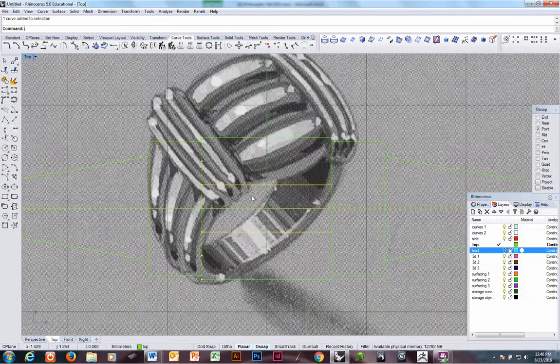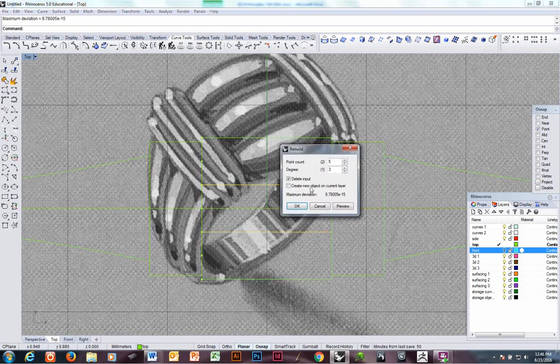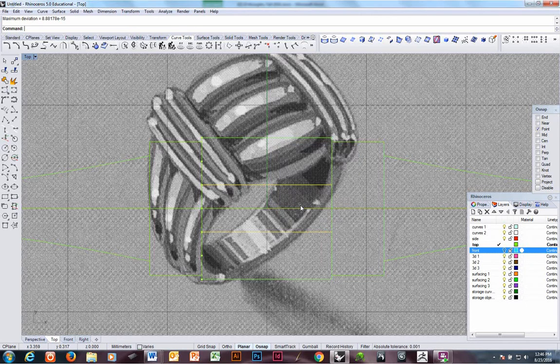And to bulge it, I'm going to do a couple of things. I'm going to make sure it's 3 points. I need 3 points, so I'm going to rebuild it, because right now it's a straight line, which is always 2, 1. I want an arc. I want 3, 2. I may change that later, but right now I want that. And then I don't want to put on my control points. I want to put on my edit points. Turn those on. Looks the same, but remember with an edit point, the curve follows through whatever you do.